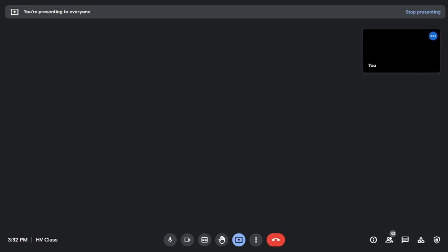So all what we did is actually we run the salt fog so that this chamber is filled with the fog, and then we place the sample which has been connected to the transformers, and then we just monitor the data measurement of this system by using data acquisition, something like LabVIEW software, to monitor and to record the data.